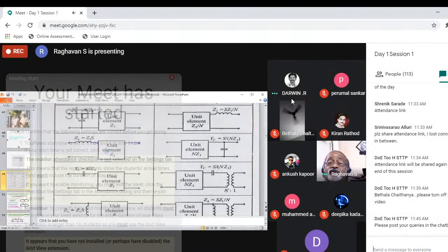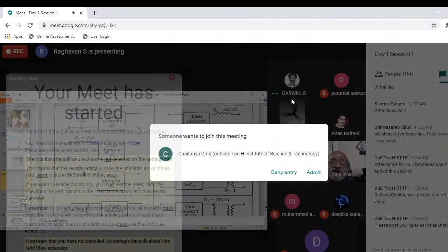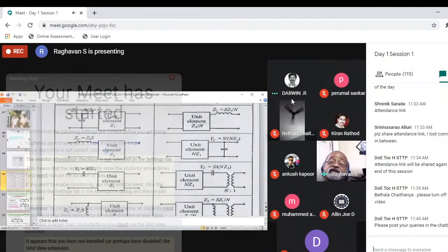I already told you that in high frequency, if you want to say two networks are equivalent, the ABCD of one should be equal to the ABCD of the second. That way, you can easily derive the corresponding elements in the Kuroda transformation. It is only two ABCDs, left side and right side. Express everything in terms of ABCD, then you can get that inductor will become capacitor, capacitor will become inductor, shunt will become series, series will become shunt.